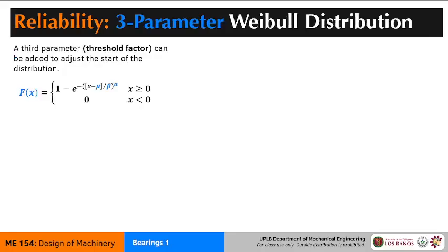So, all right, those are two parameters of our Weibull distribution. We're going to add the third. The third one dictates the starting point of the rise in your cumulative density function. We call this the threshold value, denoted by mu in this expression. So this mu controls where the rise of the Weibull distribution starts.